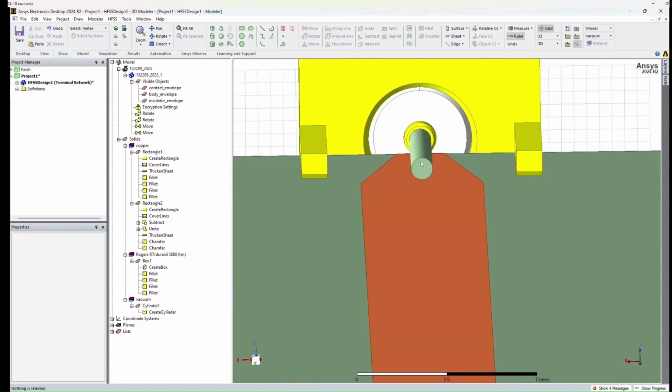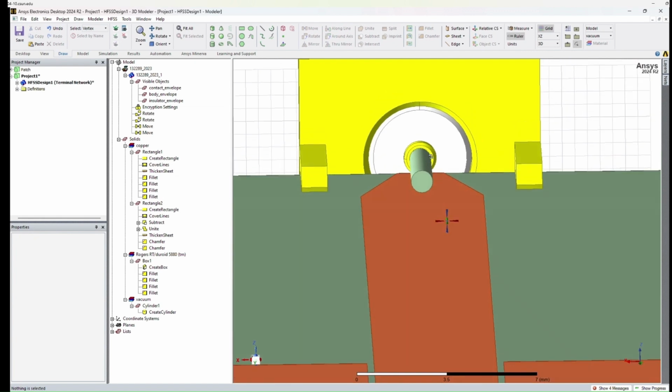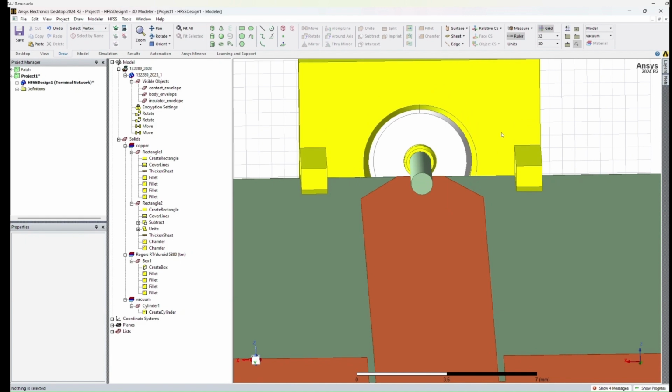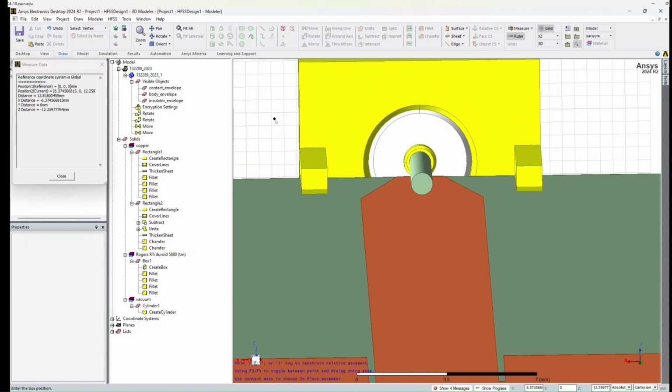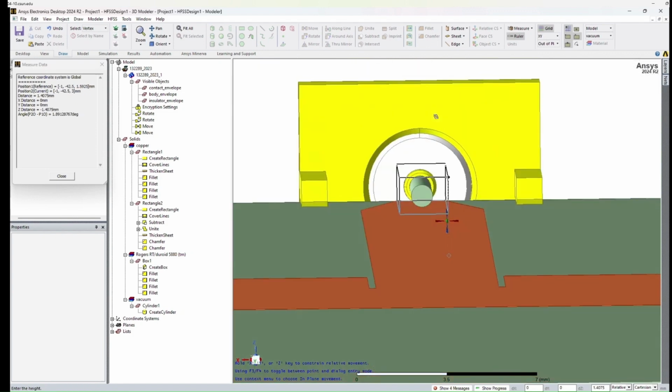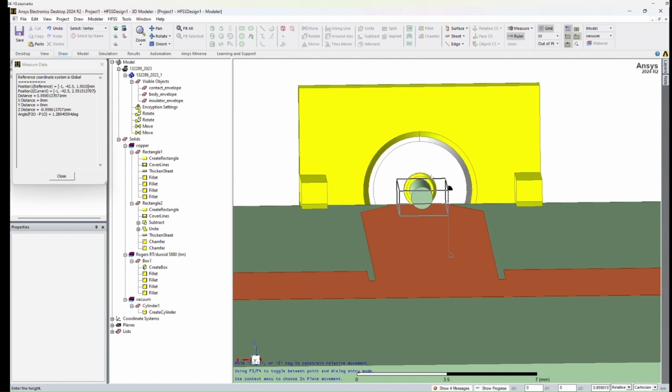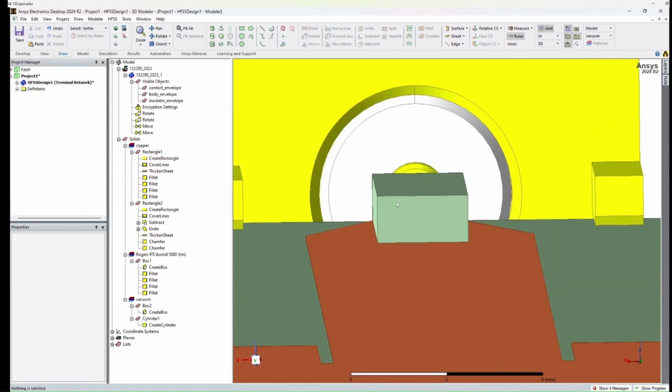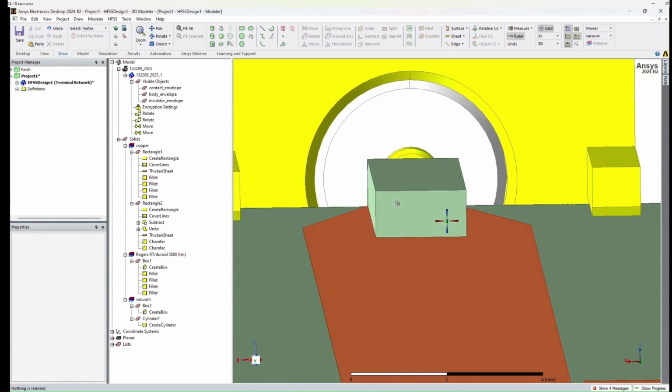And then we can use this green cylinder right here to subtract away from a larger box that will become the solder, and then the two objects won't interfere with each other. So next up, I have this box that I'm going to add. I'm going to change it back to the XZ plane and restore all of my snap functions, and then use the corners of the feed network basically to create this box and make it just enough to cover the whole signal pin right here. Okay, so now we have that there.